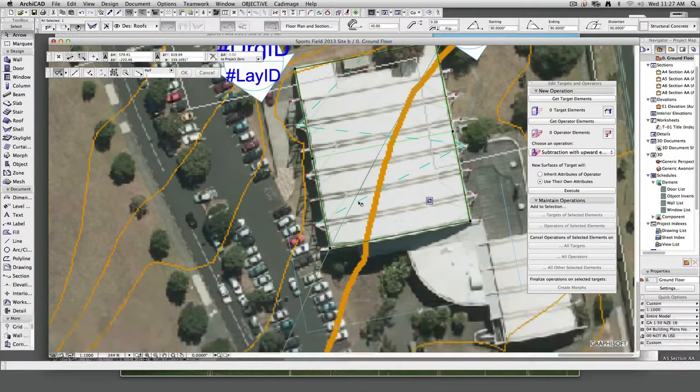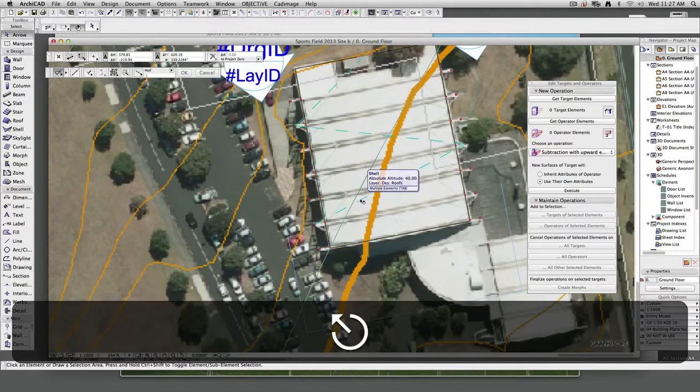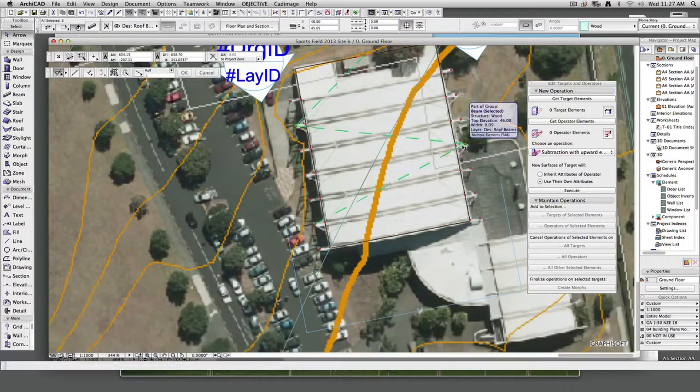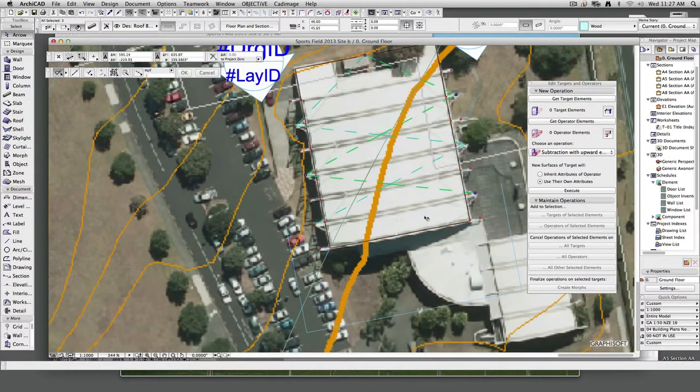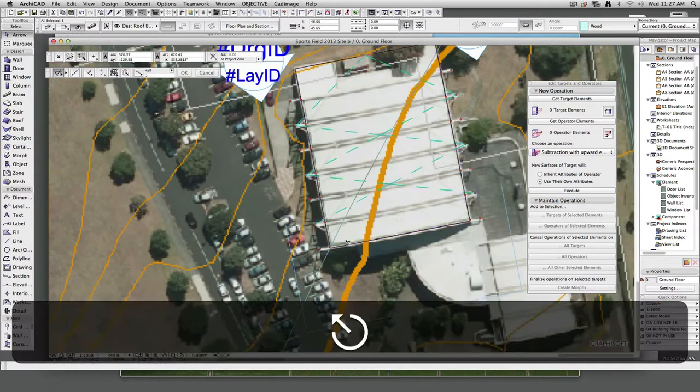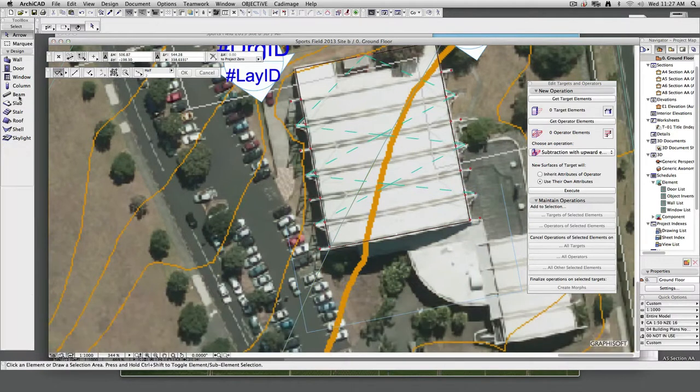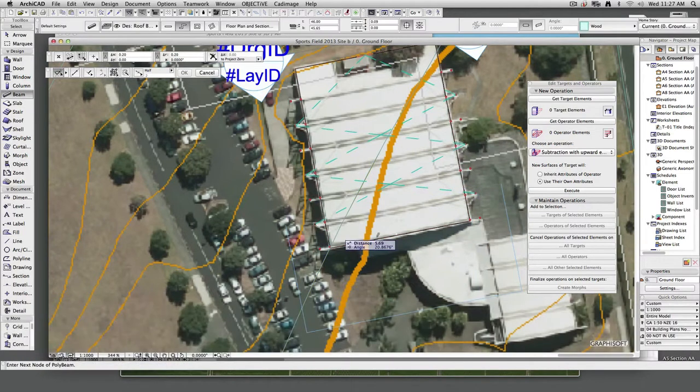Cool. Again, I can just mirror a copy of that one. So click on that node and I'll get the mirror from here. Hit the option key. Excellent. Looks like I need another beam going from here, possibly to the center.